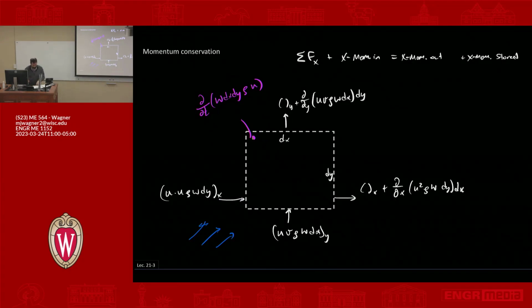So let's do an inventory of those things. I'm going to use orange here. So in this direction, I'm going to just kind of draw it anyway, but in this direction, it would be the shear on the y plane in the x direction, multiplied by the area, which is w times dx, evaluated at y.